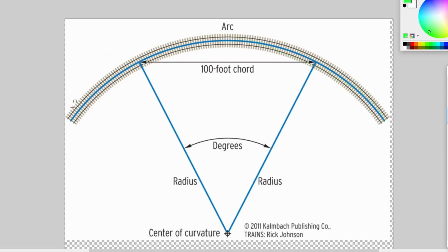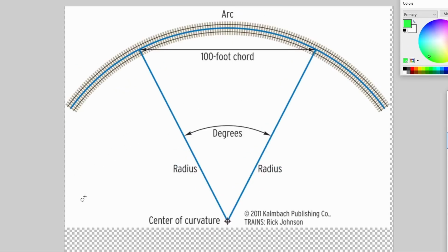We try to do circular curves for ease of things, but a lot of times things, particularly in faster applications, need to be a lot smoother because transitioning in and out of things is important. And so a lot of times you'll have a curve where rather than being this perfect circle of the same constant degree of curvature or constant radius, you'll have a straight piece of track that eases in with what's called the spiral into a sharper curve, and then it'll ease out again on the backside.